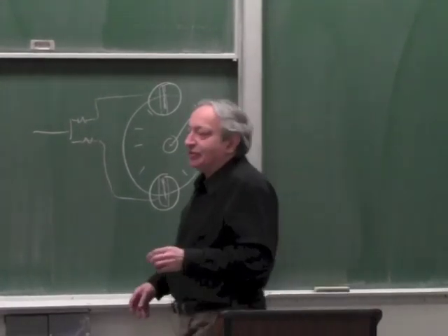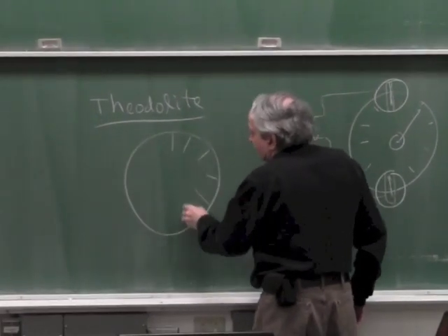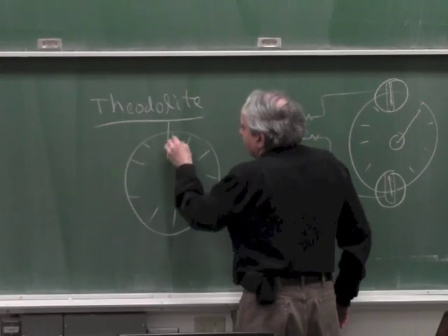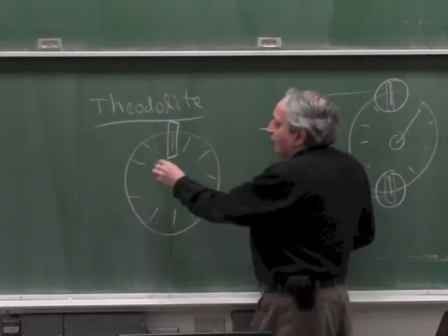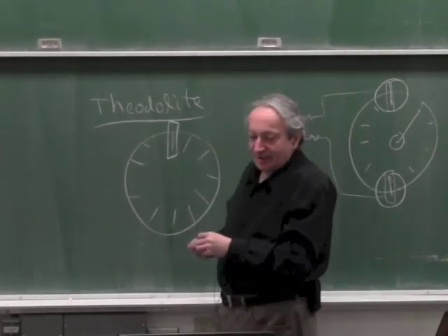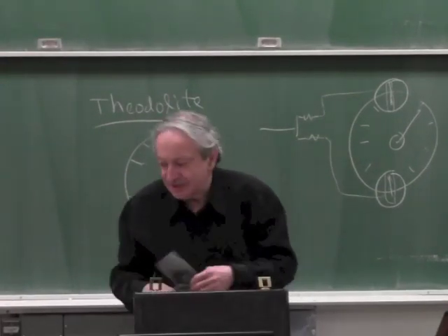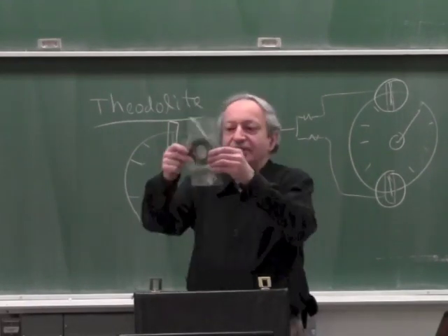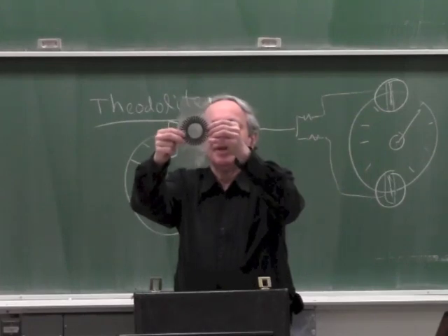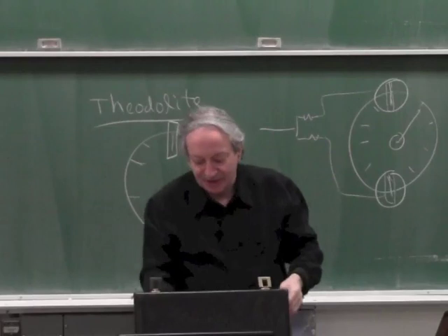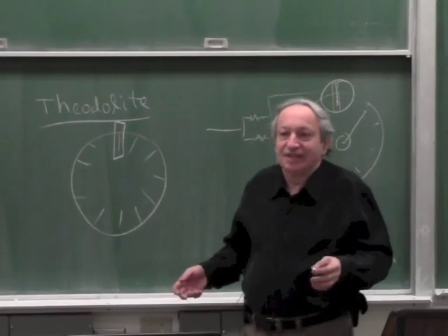The second example I gave you is that you can improve the whole encoder by, instead of taking a disk and putting a readout station, taking two disks and putting them together, and then the whole disk will be modulated. Just to remind you, I showed you two disks, and then you put them together and you turn it, and if it's centered, the whole thing goes black or white.